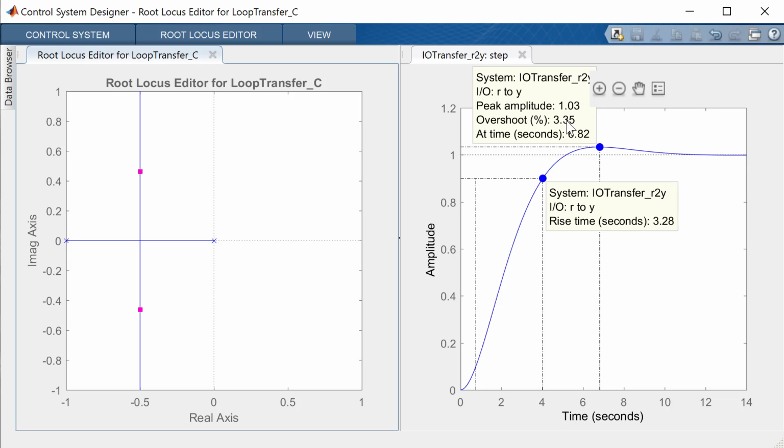This is actually telling you the real values of what this is, so these are numbers that you can directly trust. In this case, we're dealing with a second order system, and so our time domain specification geometries are going to be exact, because those essentially assume that we have a transfer function that has no zeros and has two complex poles. Once we move on to systems that have zeros or additional poles, this is not going to be completely accurate, the geometries that we talked about before, but they are still a very useful guideline for how to manipulate systems.